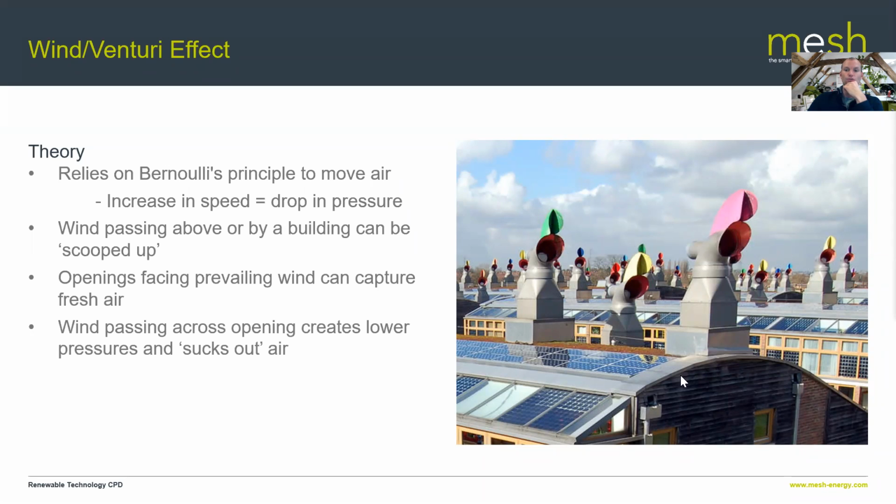that draws air from the building out and expels air up the other side, and as I say, out of the building. So again, you get this natural kind of cycle of fresh air in, and just through using the Venturi effect, you can suck stale, warmer air out of the building as well. So very, very simple. This is just one solution.